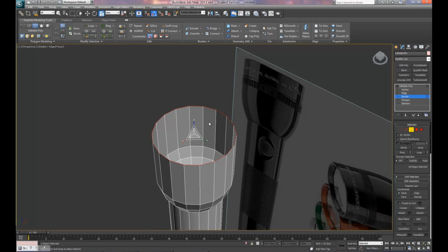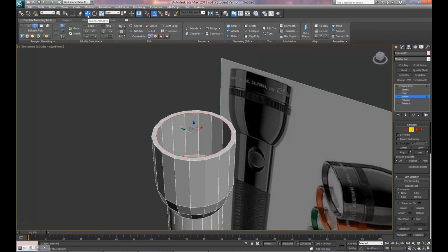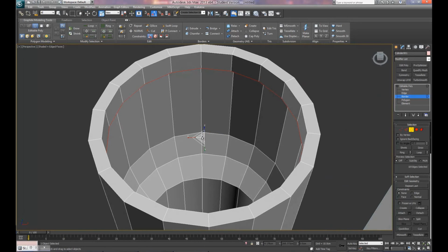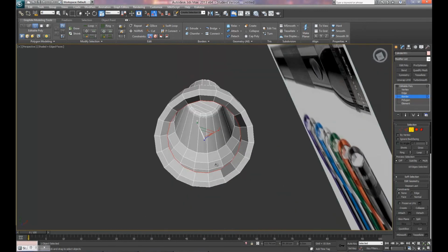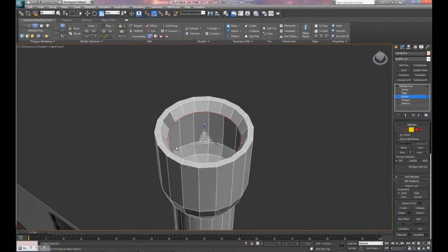So with your scale tool selected and this ring, hold Shift, and within this middle part right here, click and drag inwards, and then press W to use your move tool, or alternately move and select, or select and move. Shift and drag down, just like so. Without holding down Shift, use your scale tool, drag it in, kind of like you see in that reference image.